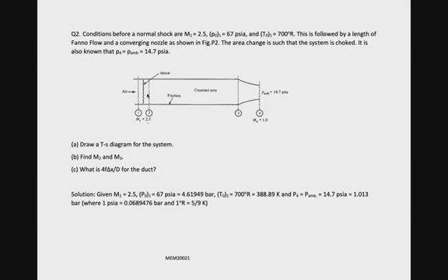As the question mentions, air after the normal shock passes through a duct with friction between the fluid and the surface of the walls, which is actually Fanno flow. This goes up to this part, as the Fanno flow is only for the constant area part. So the Fanno flow would be from this to this.